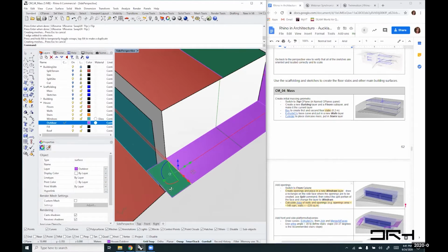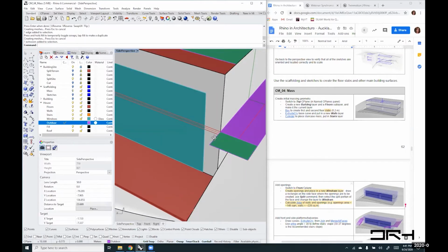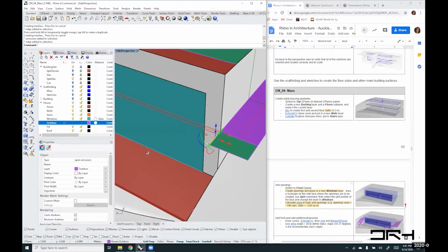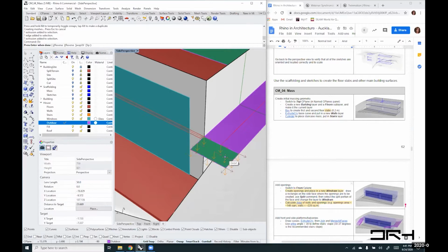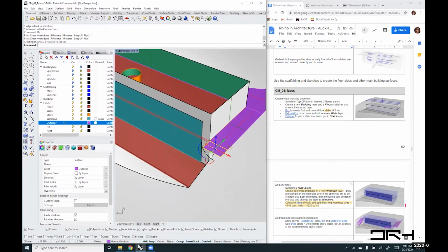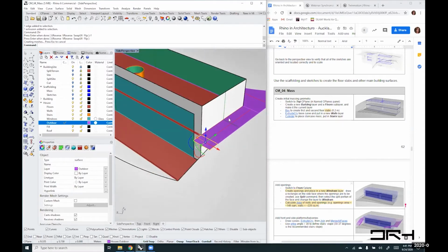And I'll show you why I wanted to extrude it, because I want to sub-select that part to create the stairs from it. So again, direction. And you see how when we assign a different color for the back face, it's very easy to see if it's back face green, and then we immediately can fix that.